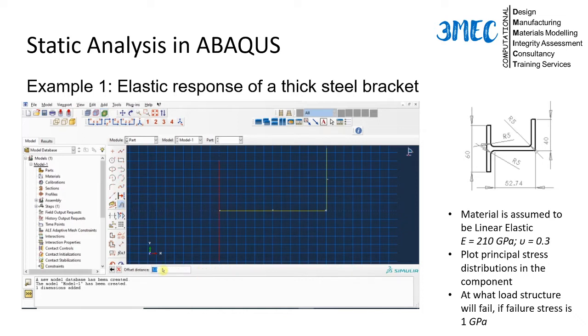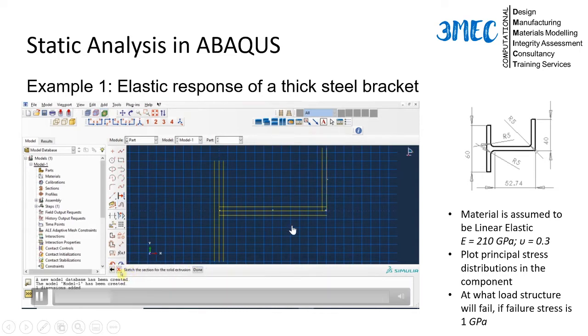So here, as you can see, I'm trying to create offsets now based on the thicknesses. On this side, again, you have to look at the other drawing views in the previous slide, but you can see I'm just trying to create those right now. Once the sketch is complete, I will create the fillets at the corners, as per the geometry on the right hand side. I also have multiple lines, so you will see that I might be struggling with the filleting. So again, pay attention to how I'm dealing with those kinds of problems as well.